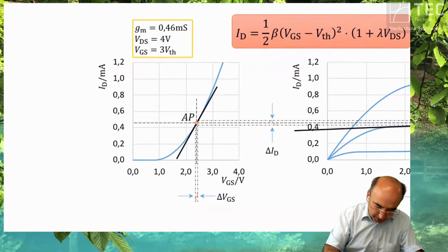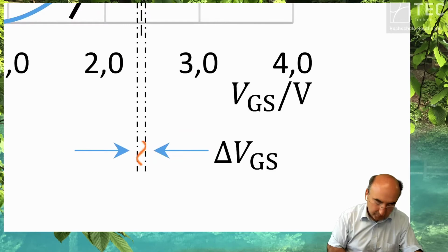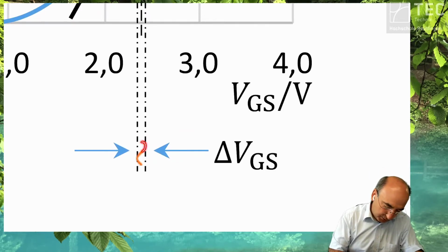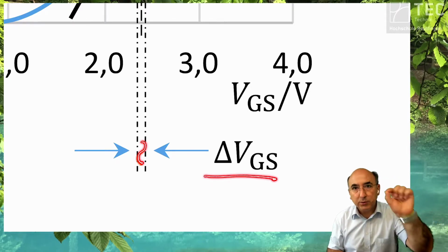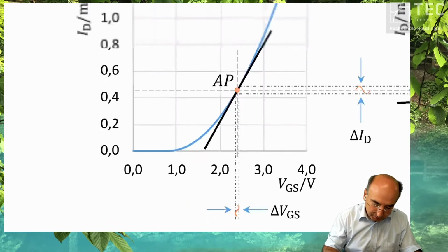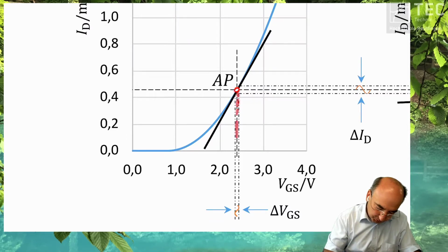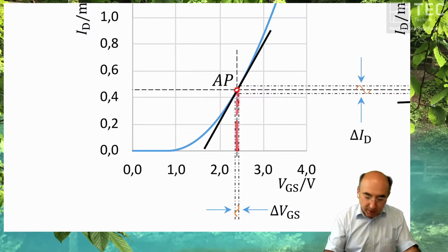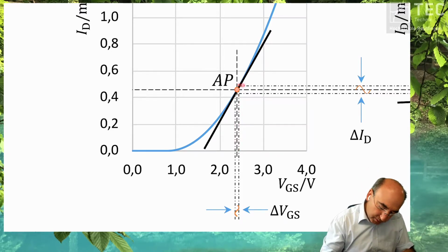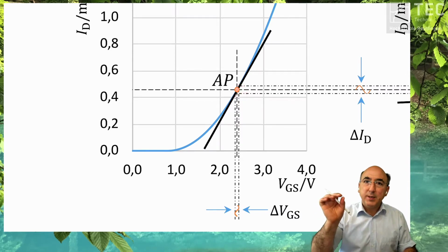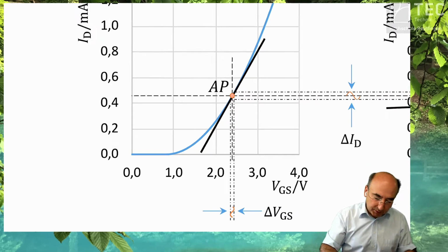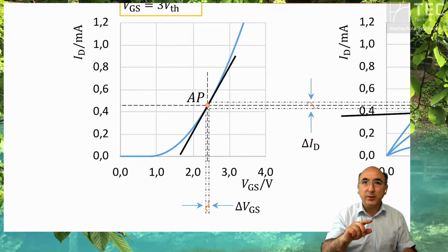That's the purpose. We want to manipulate a signal. So let's say our signal is sinusoidal, applied additionally to the gate. Additionally means in addition to the bias voltage. Then you get a certain current response at the transistor. This is the most important graph for an analog circuit designer.